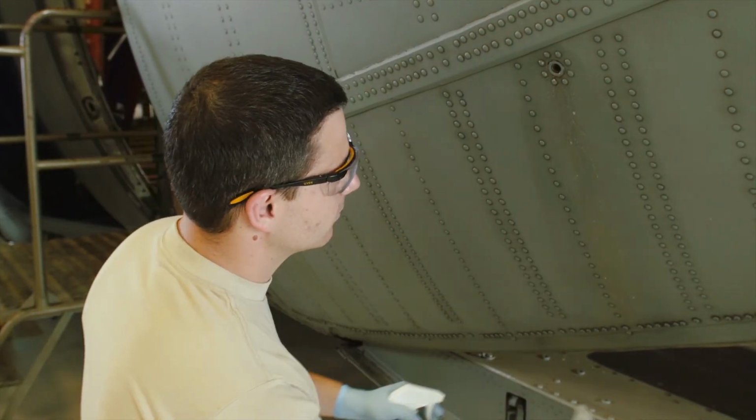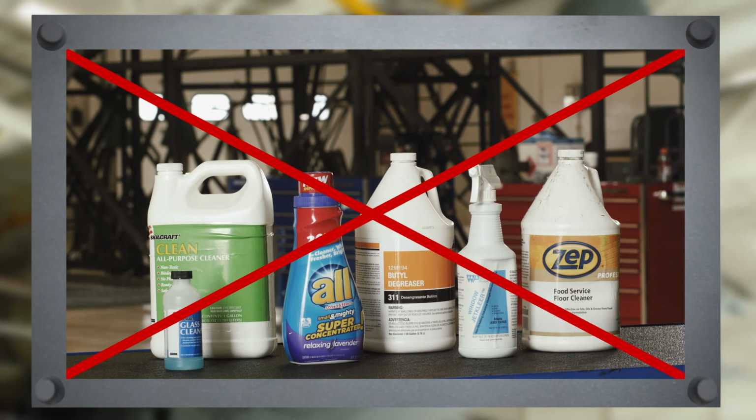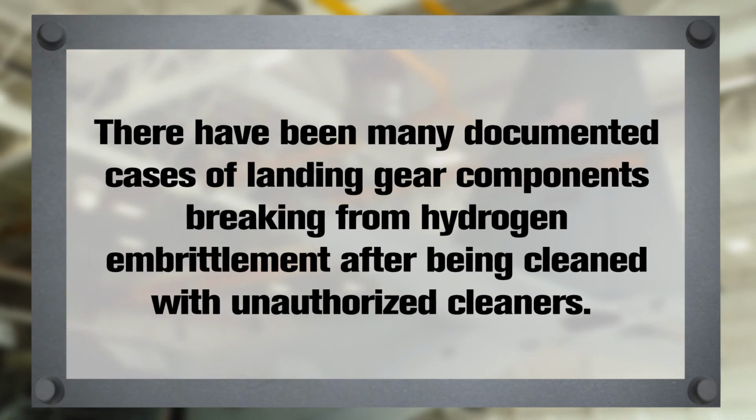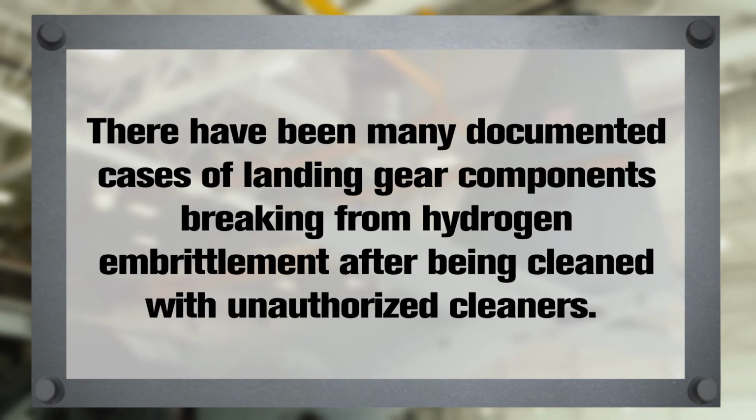Performing frequent surface wipe-downs is just as important as performing scheduled cleaning, and can actually cut down on the time you spend washing. It is critical that you use only TO-authorized cleaners for spot cleaning. Currently authorized spot cleaners are available in convenient pump or aerosol spray containers. Using unauthorized cleaners can promote accelerated corrosion rates on metal surfaces and cause hydrogen embrittlement on high-strength steel alloys. There have been many documented cases of critical landing gear components breaking from hydrogen embrittlement after being cleaned with unauthorized cleaners.